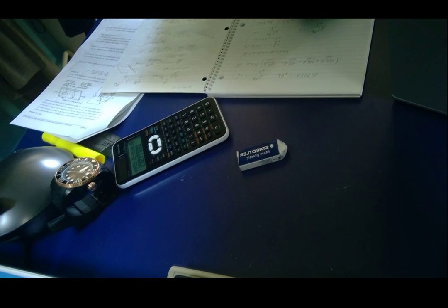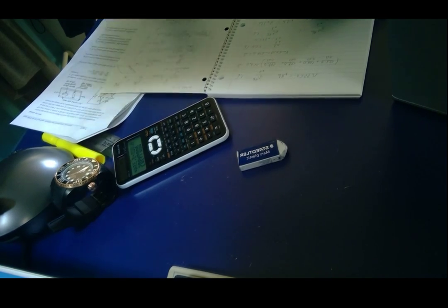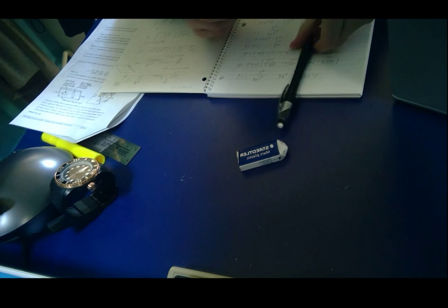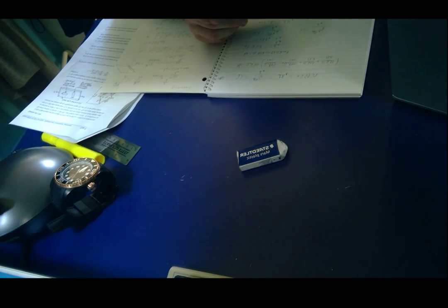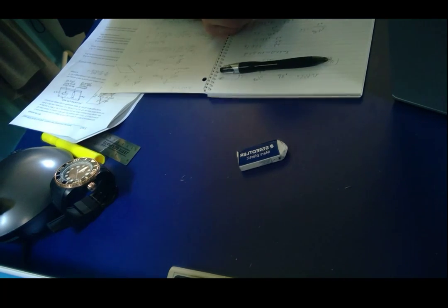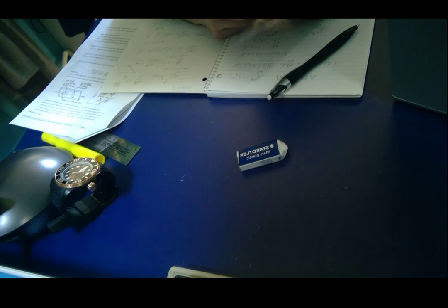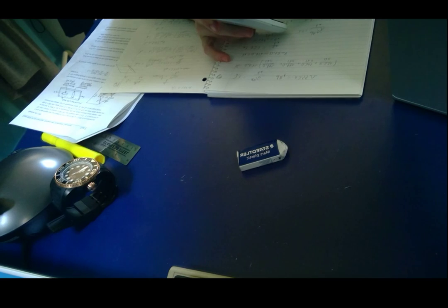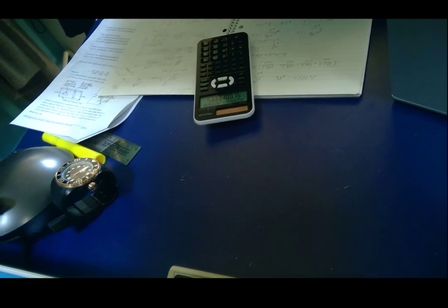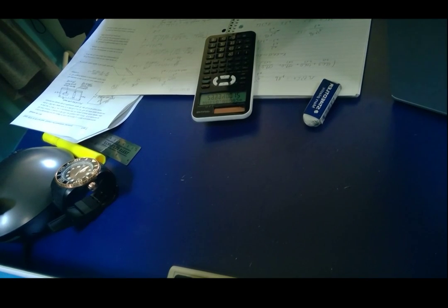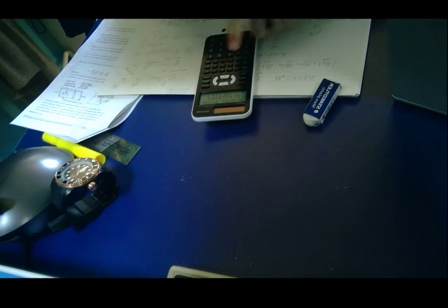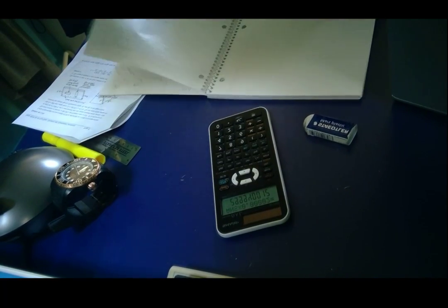we'll see that the 200 times 10 to the 9 is equal to the stress over the strain, in this case 0.0075, multiplied by 200 times 10 to the power 9. It gives us a very large number. And now we'll multiply this by the area, where 0.00002, and that gives us a sigma, a F, a load of about 30 kilonewtons. And that's question 4.